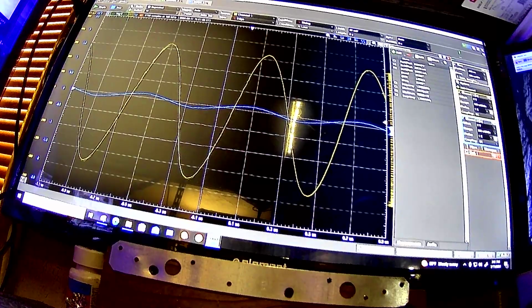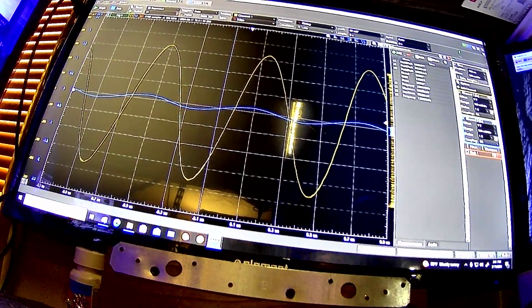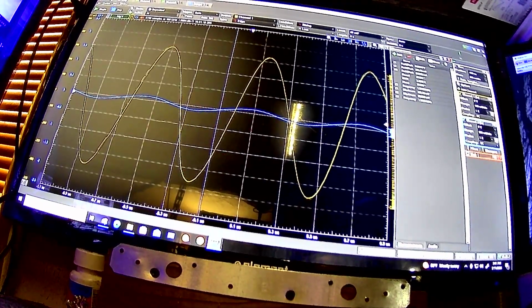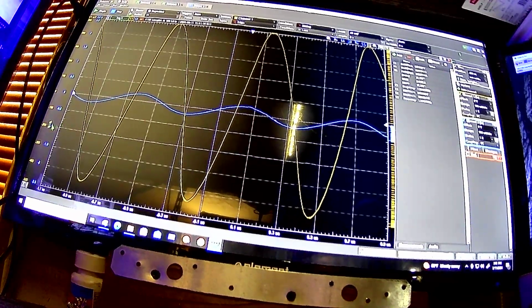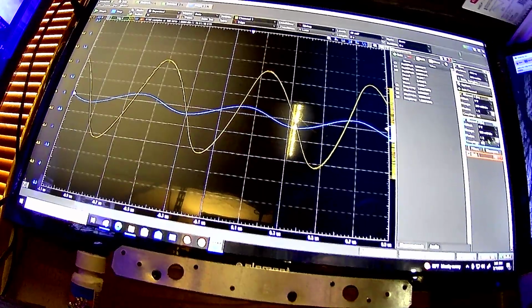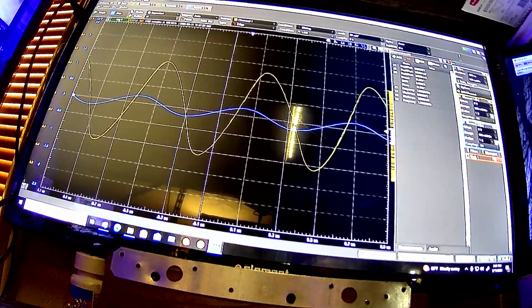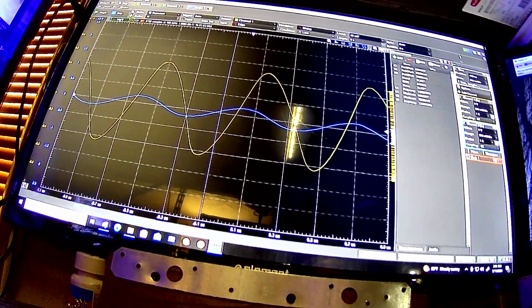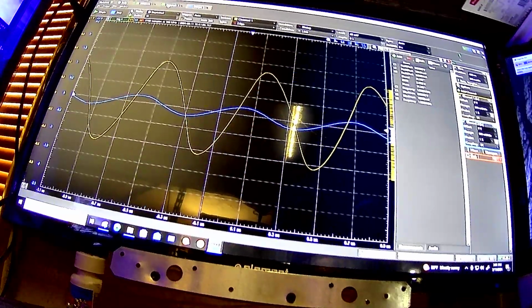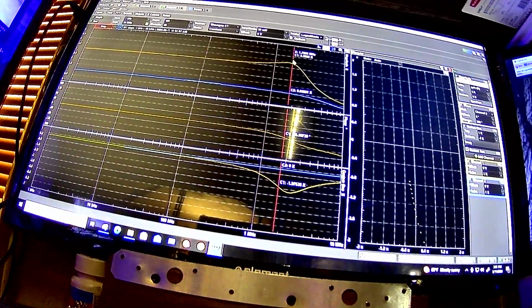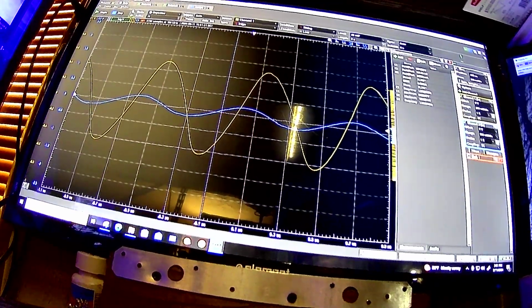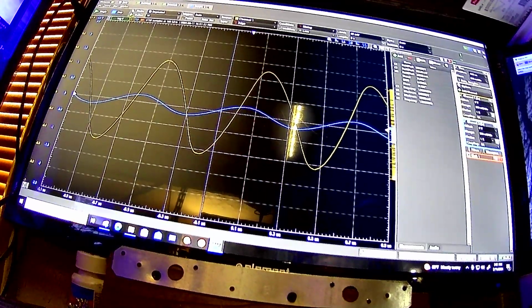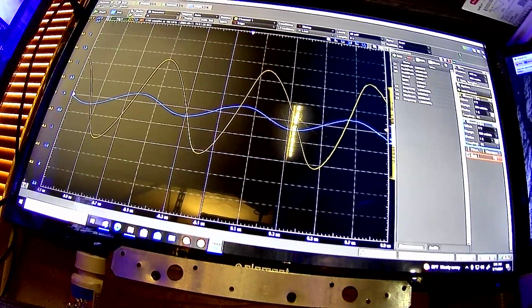Upping it, peak to peak output is 680 millivolts. Okay. But like I said, supposedly our gain's higher here, right? What is our gain? Because according to this, it says our gain is actually 3.3 at this point. So, see if I can adjust it to an amplitude that gives us anywhere near that.